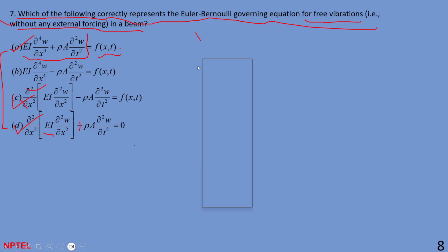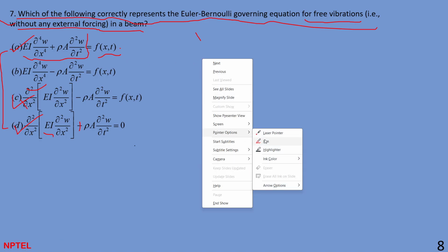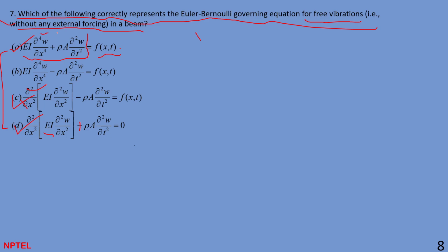So you see, the LHS represents how the deflection of a beam is happening, and the RHS represents the external force. Let's say if you have a link, it is something like this. It is governing how the link will bend. This is delta W, the deflection we are talking about, and this is density and the area of cross section.